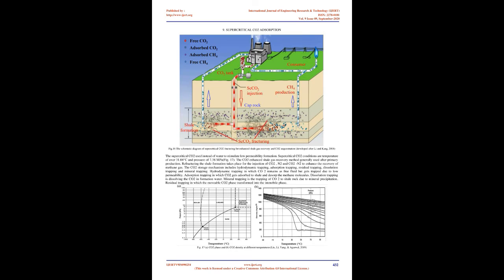The adsorption-induced swelling strain in shale will increase sharply at initial pressure and then increase gradually with increase in pressure. Surface area, pore size distribution and porosity get reduced under the influence of CO2. The intermolecular repulsion forces between sorbate-sorbate and sorbate-sorbent molecules will induce pressure increase in the pores, which causes the adsorption-induced swelling strain to increase rapidly at the initial stage. Shrinkage on the basis of adsorption rate, Chen, Feng, and Pan, 2018.